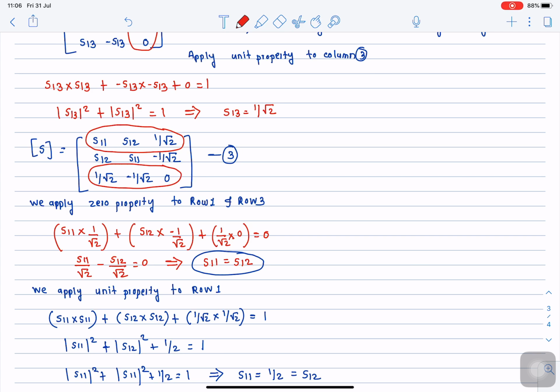of the microwave signal. Now you may ask what is the typical application of these 3-port junction devices for which we just developed the scattering matrix equation. See, rectangular waveguide T's are used as a tuner circuit by placing a short circuit in the symmetrical arm. These devices can be used as power dividers, and also as adders in duplexer circuits.